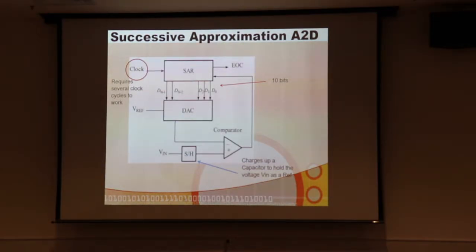So what happens when your signal is changing very rapidly and your capacitor is changing charge in the middle of it? You are band limited. There are frequency components that will exceed the capability of this chip. Anything over about 1 or 2 kilohertz will probably do that. And then what happens is, according to Nyquist, that sampling will be folded back in. You'll see an alias signal folded back into the bandwidth you can measure, and it will fool you into thinking that you're actually seeing the signal when actually you're not. You're seeing an aliased signal.